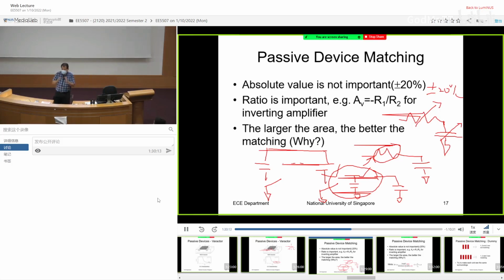To do what? If the capacitor value turns out to be very big, you turn off the capacitor, only keep one of them on. So the capacitor's value becomes smaller, and you can move the cutoff frequency back to the normal position. If your capacitor's value turns out to be too small, you turn on more capacitors so that you can move the cutoff bandwidth back to the normal position. So to tackle this kind of process variation, component variation, usually you have to know what kind of variation you expected. So when you design the programmable value, you will try to take that into consideration.